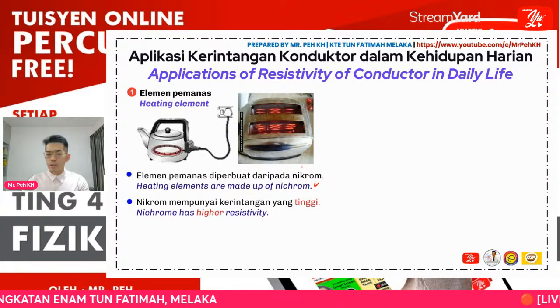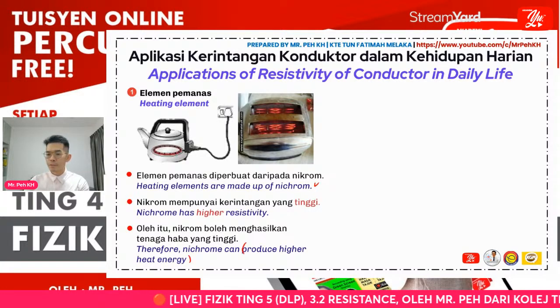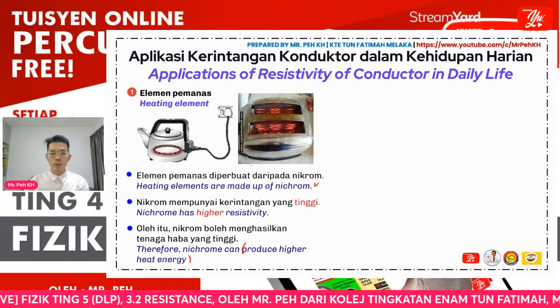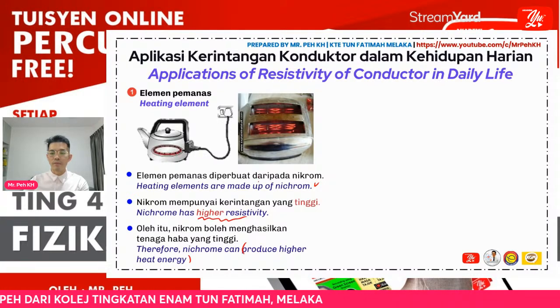So this will provide higher heat energy, producing heat. That means for applications where we need to produce higher heat energy, we have to choose a material with a higher resistivity.